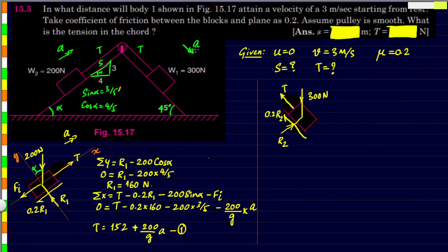And lastly, of course, last time we had forgotten to take the inertia force. Let's take that as well. So inertia force will also act opposite to the acceleration. Acceleration is acting downwards, so inertia force will be acting upwards.